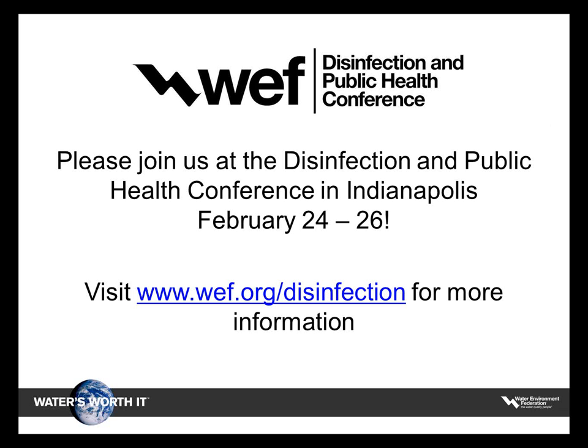Okay, Dave, I've got one more question for you, I think. On your system that you have installed, is the dose varied based on water quality or the UV transmittance, or is it just flow pace? We have a combination of flow pace and transmittance. We monitor both. And so that's automatically changed, or is that manually?